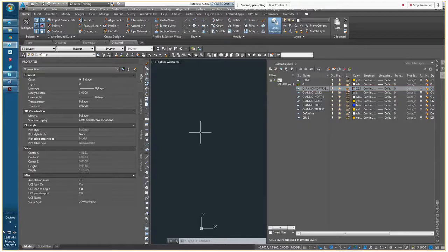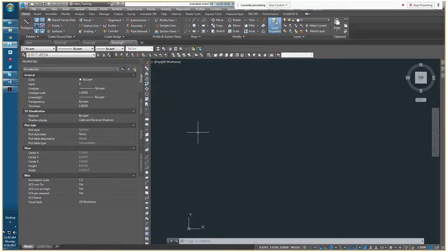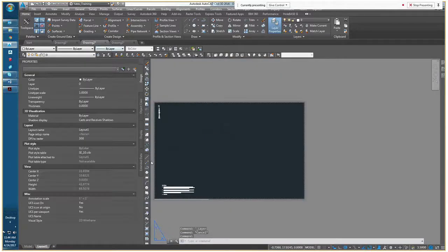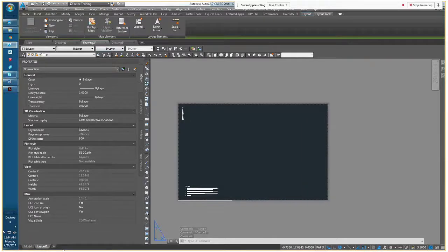So that is our 2 basic templates, the Civil 3D and the detailed DWG templates, and I'm going to tell you now what we use each one for. Basically, if your drawing contains a surface and alignment, COGO points, profiles, profile views, sections or section views, pipe networks, or parcels, you're going to want to use the Civil 3D template.